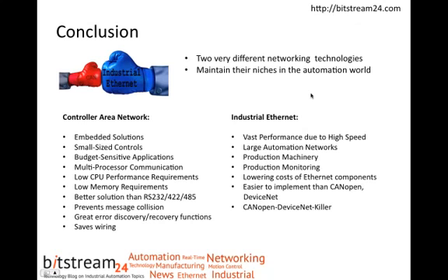Even a low-cost RS-232 solution will not be as cost-effective as CAN, and on top of that, CAN provides great features such as error detection, error recovery, and the prevention of message collision. In compact multiprocessor systems, CAN will reduce the amount of wiring significantly, and thus increases the reliability and reduces maintenance and troubleshooting efforts.